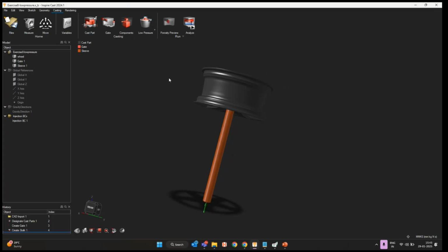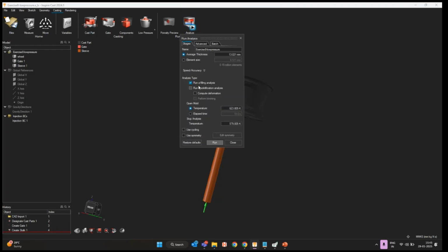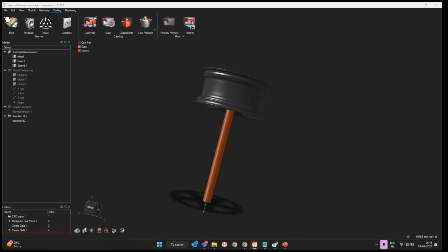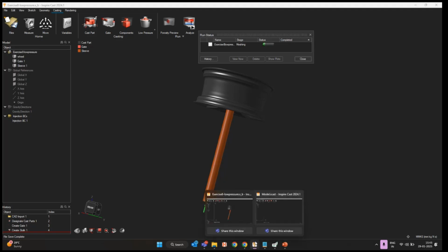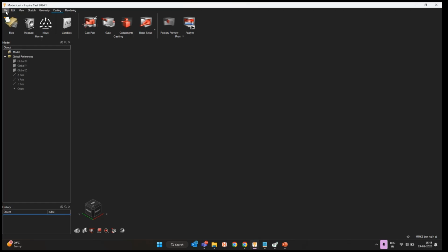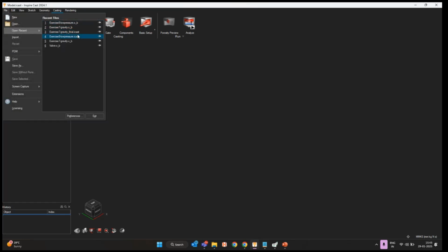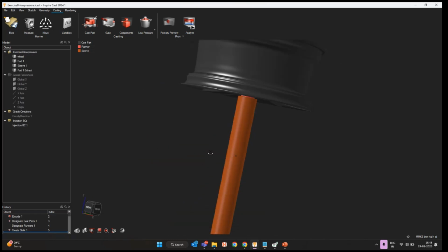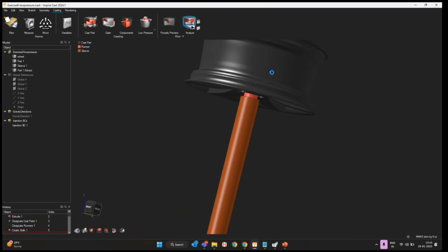Once I specify the pressure parameters for the flow, I can just click on run. Okay, sorry, I need to run this. So here you can specify both parameters. If you want faster results, you can provide the element size here, maybe as 10, and then you can run the simulation. Since this particular analysis will take a bit more time, I already have the results available with me. So I'll open those results. I have this particular model which is already run. I'll directly go to the result view.